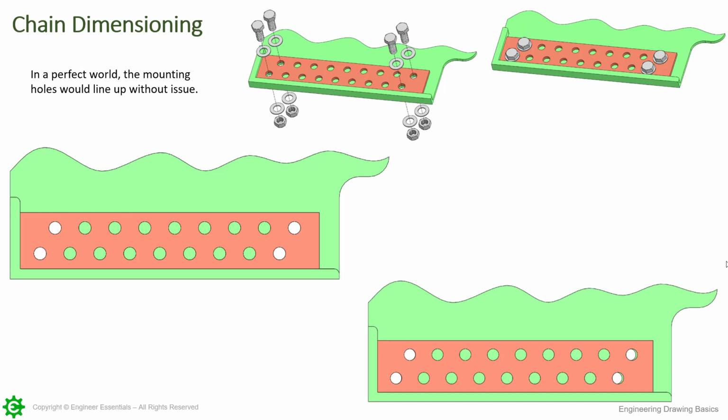If you look up at the top, I'm showing just a simple bus bar. It's a copper plate, and notice how we've got a rail coming around here. So this is the two rails, sorry. This copper bus bar is going to go into this assembly. So any kind of drawing we ever make, we need to look at the assembly requirements, or the function of the component, to fully determine how we need to dimension the part.